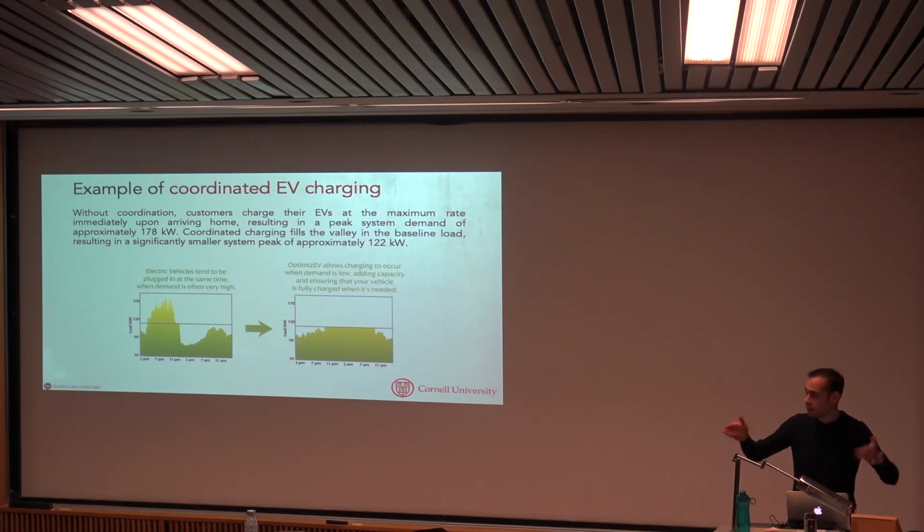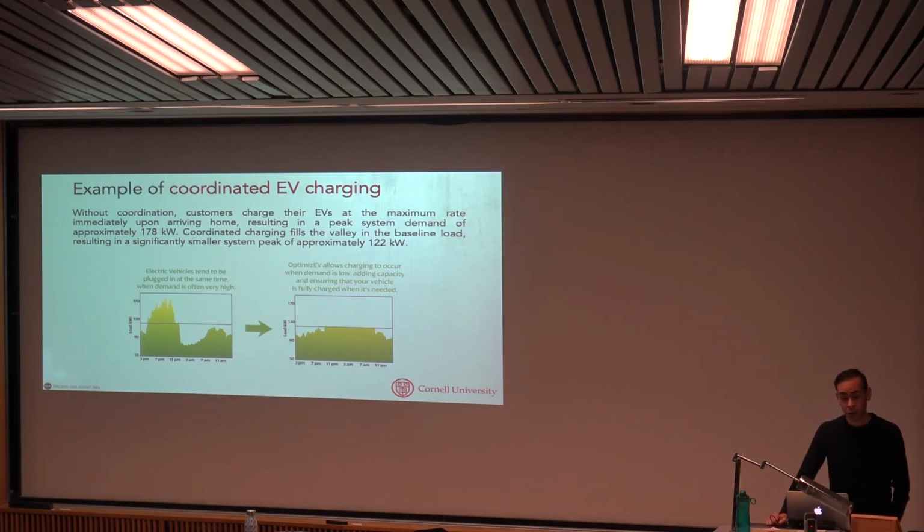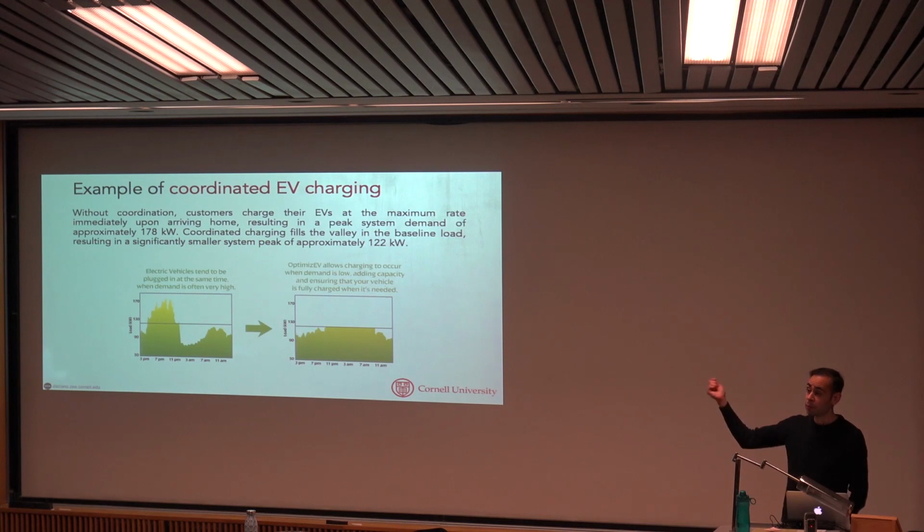The idea is that instead of having that peak load when people are charging without participating in this type of program, when they do participate and allow the utility to delay the charging, you flatten the load and avoid creating that stress that would happen with that peak in the load. So you can think, okay, maybe there are other solutions.